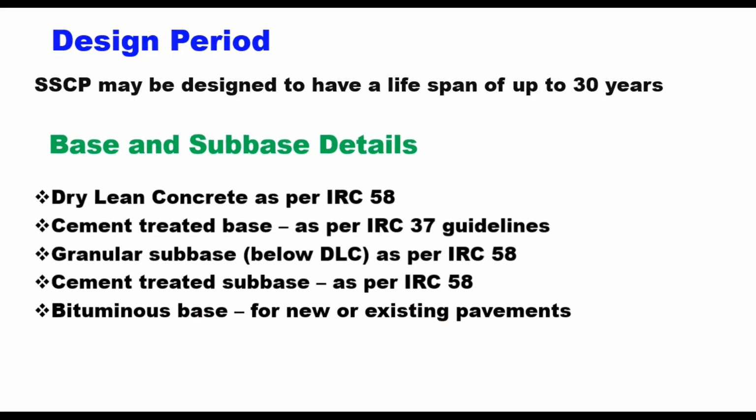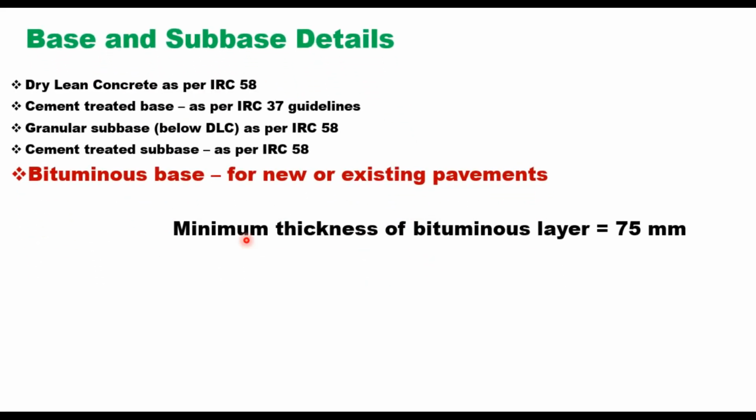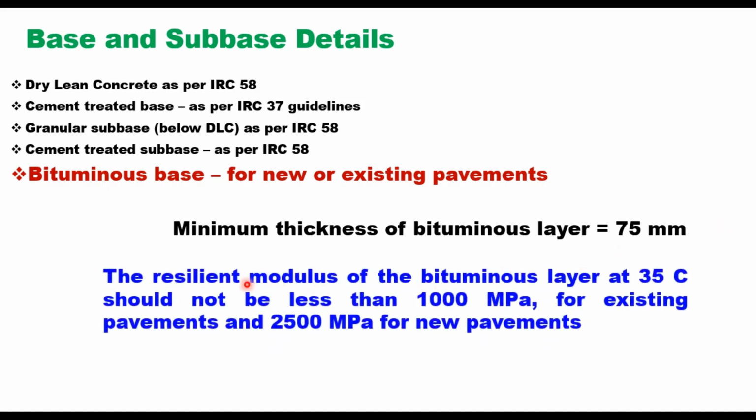And when this bituminous base is considered, then minimum thickness of bituminous layer should be 75 mm. E value or resilient modulus of the bituminous layer at 35 degrees centigrade should not be less than 1000 MPa for existing pavement and 2500 MPa for new pavements.